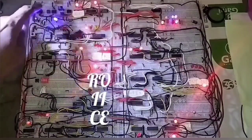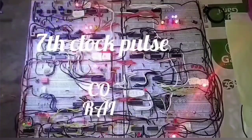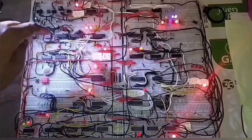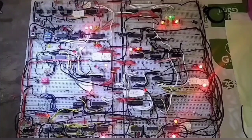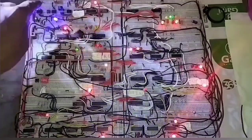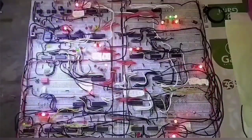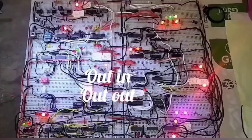The first step is program counter out and memory address register in. The second step is RAM out, instruction register in and counter enable. This is the fetch cycle for every instruction. For the load A instruction, load B instruction, and jump instruction, the execution cycle is counter out, memory address register in, RAM out, and that particular register in.